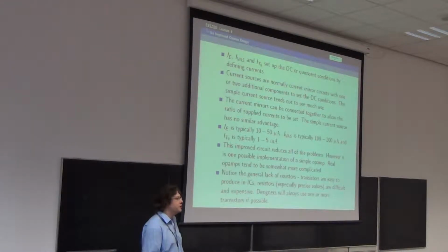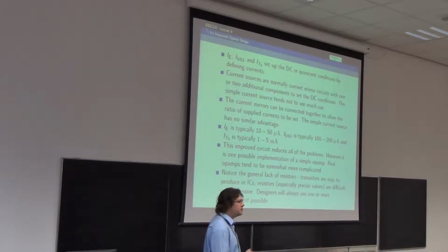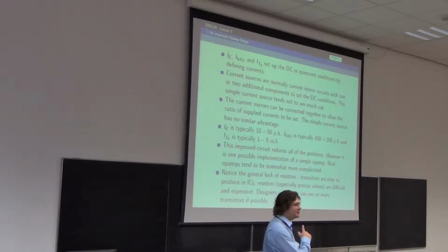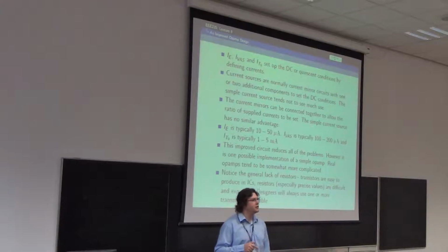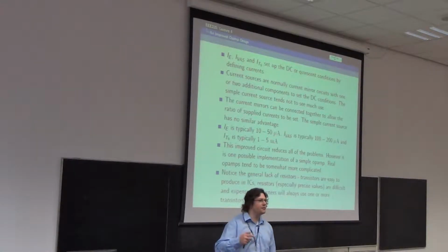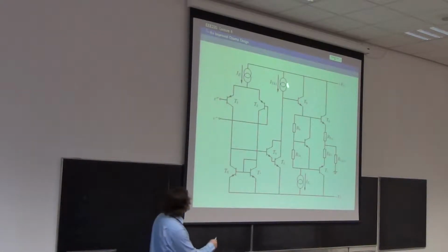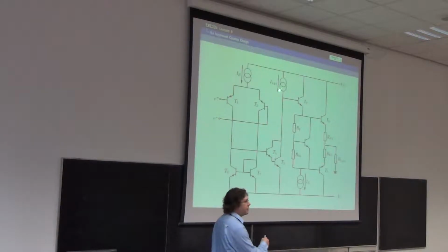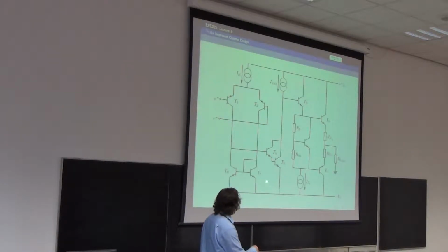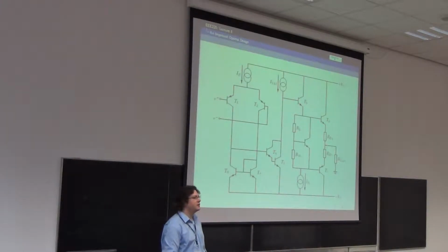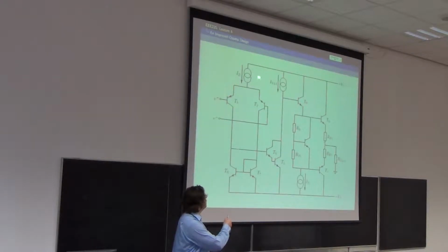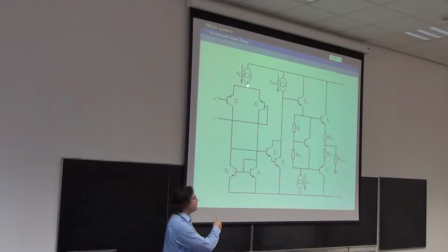But also we can use a mirror, and if we do use a mirror, we can use a mirror to mirror a mirror. You'll see this in a bit. And if you put a resistor in the right place, you can choose a ratio of currents to flow through the mirrors. So you can have a mirror for this stage, which gives you, say, 5 milliamps, and you'd mirror this current somewhere down here in a circuit that doesn't exist, and mirror it back to there, but you put a little resistor down here in just the right place, so that if this is 5 milliamps, this will be 500 microamps. And if this is 1 milliamp, this will be whatever the same ratio is.